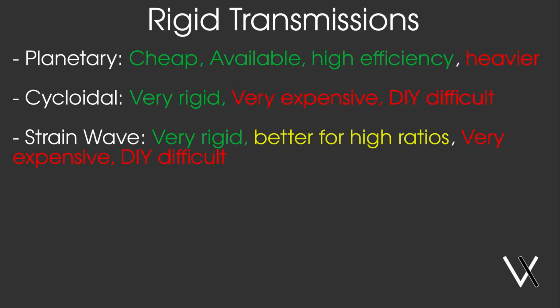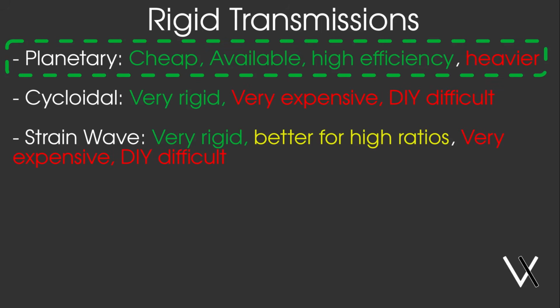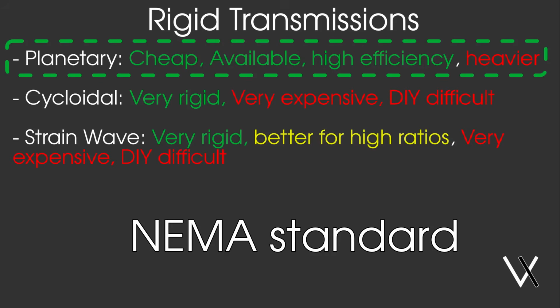Planetary gearboxes are the clear winner here for us. They're produced by many manufacturers in the NEMA standard sizes that are commonly used with stepper motors, so we'll have a lot to pick from.